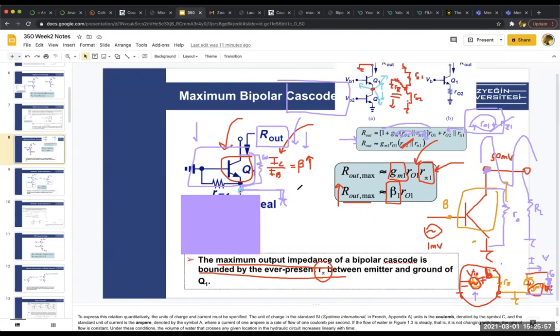And when you design a chip, these are the things you deal with, because in a cascode this is not, of course, ground here, but in an actual circuit, you will see a capacitance here. That's called parasitic capacitance. Let's assume that you are designing a CMOS imaging circuit at 100 gigahertz. What is the impedance of this cap? It's 1 over j omega c.